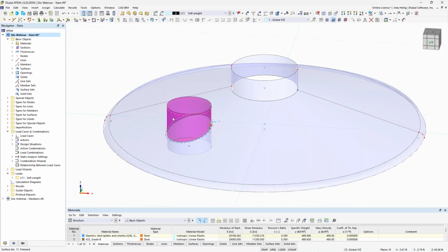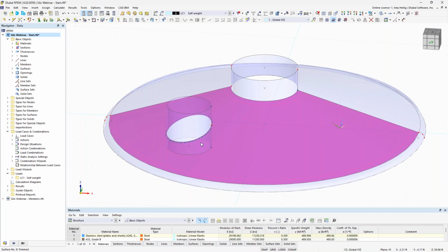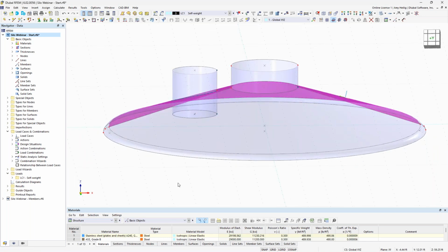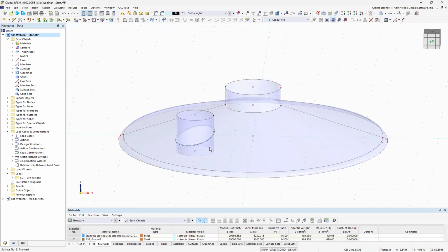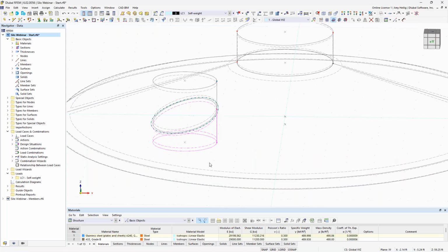The program also broke apart this vertical surface into 2 various parts. So if we'd like to delete everything below the curved quadrangle, we can go ahead and turn this to wireframe view, and I can graphically use my selection options here and simply hit delete on my keyboard.